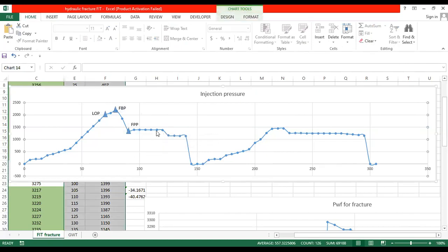And then once you come close to the end of constant pressure, we have to stop injecting. Once you stop injecting, it means you are not giving additional pressure. This is what we name as the shut-in condition. So from here onwards, shut-in condition starts. This is the point, initial shut-in pressure, where the pressure has reduced because we are not injecting fracturing fluids right now, but still the fracture pressure was maintained for some more time.